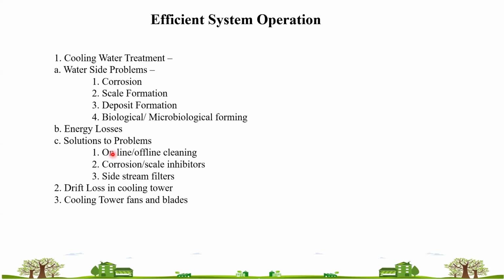I'll give an example. You can always save energy in a cooling tower where there is no direct process impact or direct energy impact. What happens when you control fan power with the help of a VFD or on-off control? The rise in temperature of the cooling tower water will deteriorate the performance of the connected equipment.